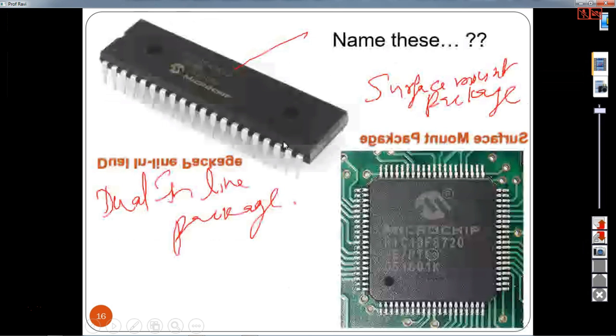And the features of this, if you try to see, it has 35 instructions only. And integration of operational features: power on reset, that's what we discussed, and brown out protection. So this is what A stands for, brown out protection. So this ensures that the chip operates only when the supply voltage is within specification, within specified voltage levels.